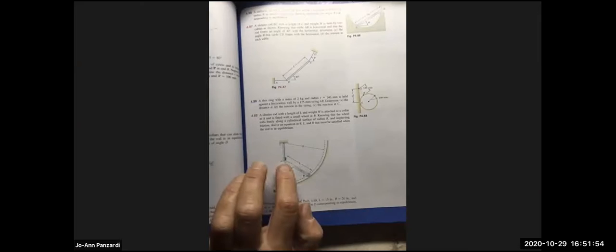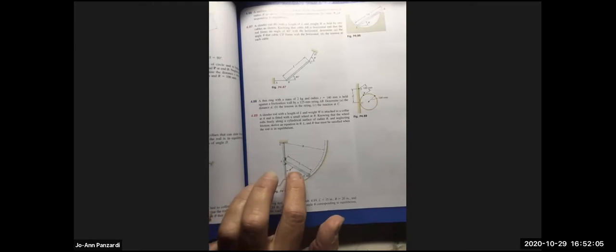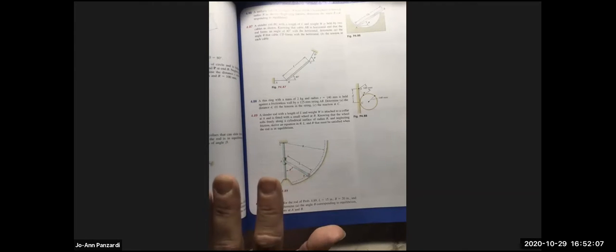Is there a 2-force member here? Jason, is there a 2-force member here? The roller rod. Right, this rod right here, because it only has a pin here and a roller. Unless it has weight. Well, if it has weight, then it's not a 2-force member. That's a really good point.